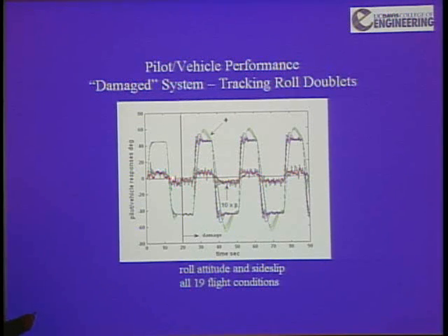This is the side slip variation. You'd like to see that right along 0. But we're getting a little bit. That's 10 times beta. That's a very small side slip. And the pilot's not doing anything, feet on the floor. So this is an example of why pilot models are useful. You can do a design, then you can do an evaluation, and then if you're confident in the design, you take it to pilot in the loop simulation or flight test.